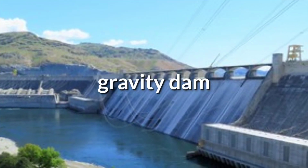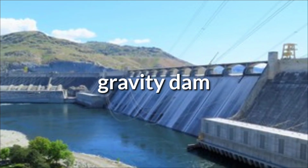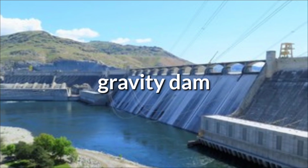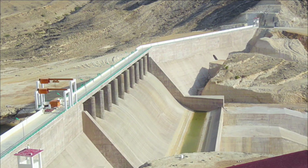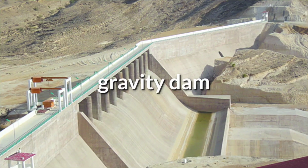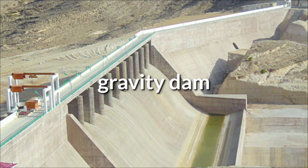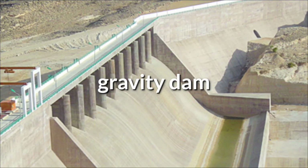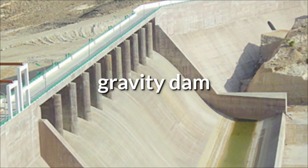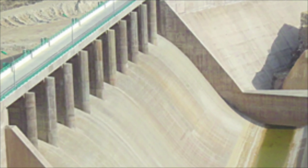New masonry dams of both gravity and arch designs are being built in India, China and other lands where the cost of labor is low. It is adopted to prevent sliding and contact with the foundations, and the foundation itself must have appreciable shear strength. In carrying out the stability calculations for the many proposed sections of the dam, the uplift must be taken into account.